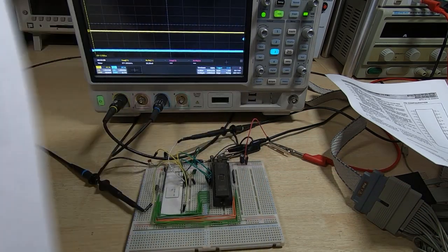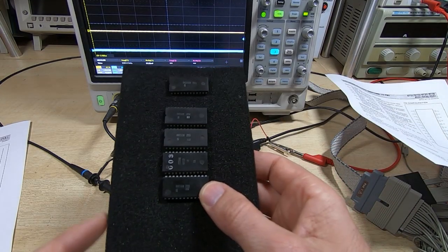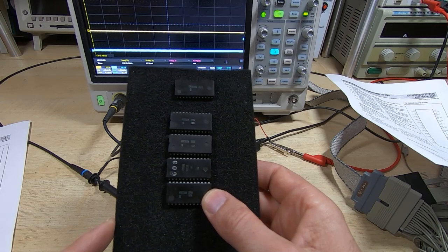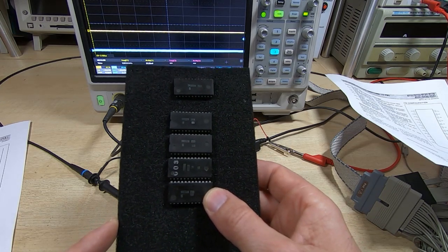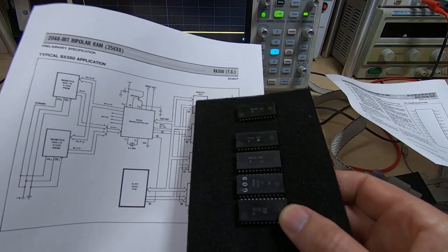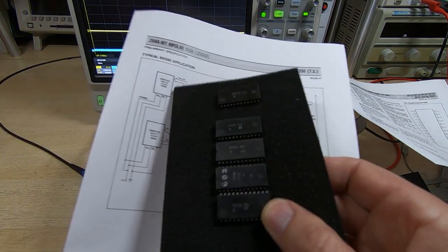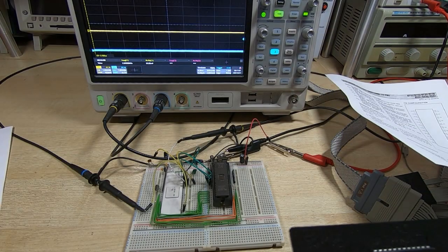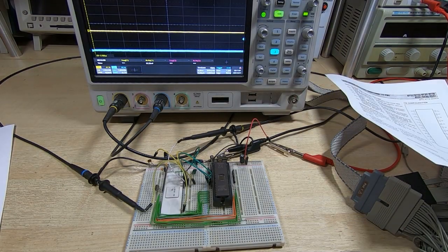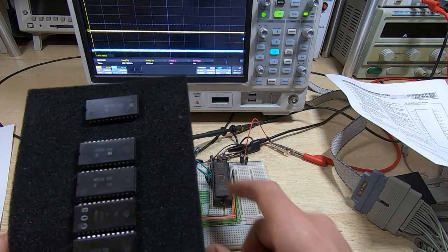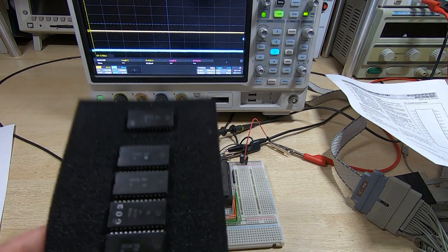So what I need to do is get these hooked up. There's a few control lines, but as I say, it's mostly hooking up the address and data lines. As I said, these are the address and data lines on the same bus, not to be confused with the address and data lines for the ROM. So I'll get that done, I'll get back on camera and see if we can get this to actually do anything. Before it will access these, of course, we will have to go back to the assembler and write some more code.